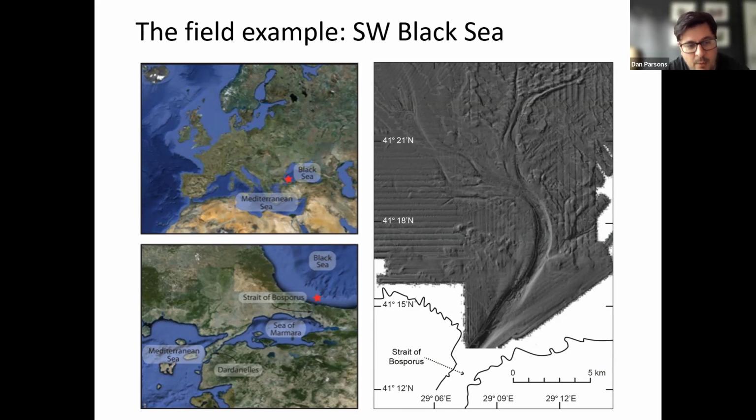There's an exchange flow that runs pretty much 24/7, 365 days a year, slightly perturbed by atmospherics at times in terms of pressure patterns, but in the main we have a denser, more saline flow at the base of the Bosphorus Strait, going from the Sea of Marmara into the Black Sea, and then there's a less saline return flow at the surface of the Bosphorus Strait, moving from the Black Sea into the Sea of Marmara.